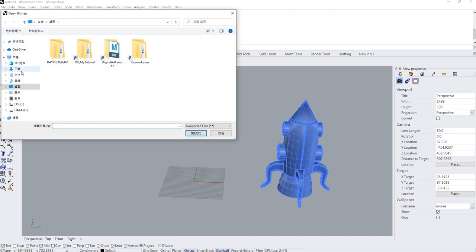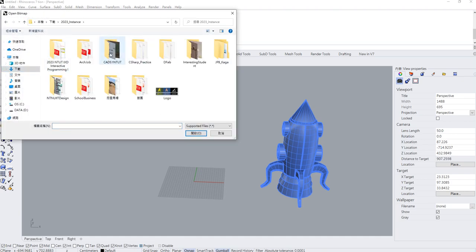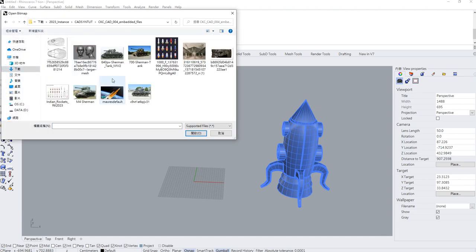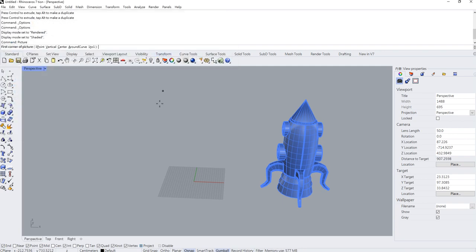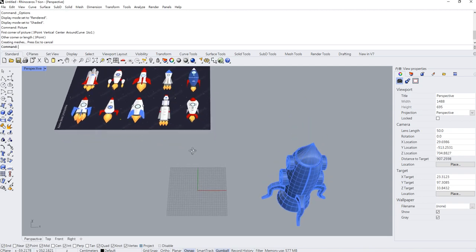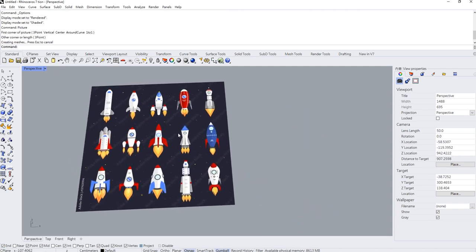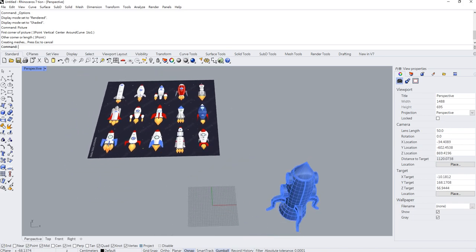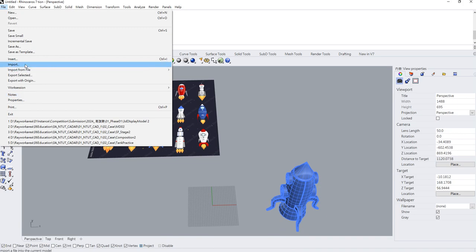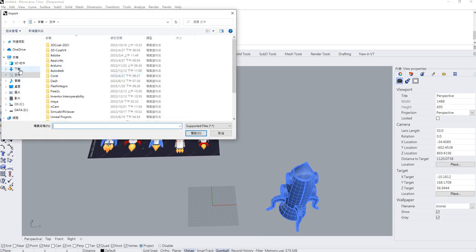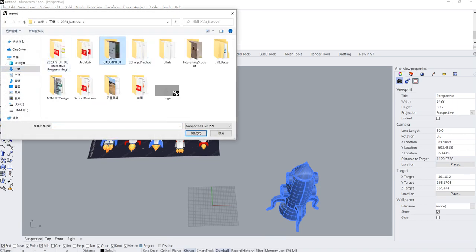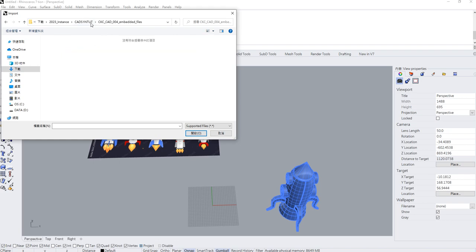So that's our target. So let's go to shading mode again and using the command bar, type in picture, right? I have already found some references, so I'm going to import them and you can import yours. First thing I'm going to import is this cartoon rocket side view, so we can use all these elements in our rocket design. And also, I found some realistic rocket images that can be our reference.